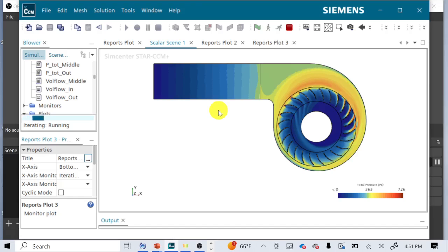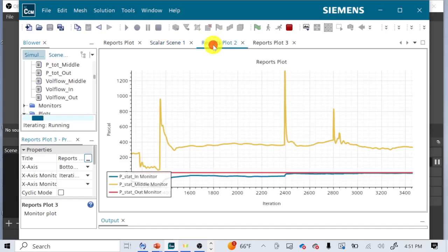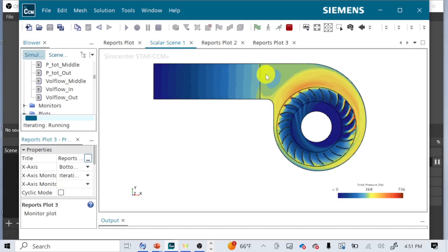Right there. So we're looking at the delta pressure across primarily this, but we should measure it at the inlet as well to make sure we know what's going on. So again, delta pressure across this outlet resistance section is what we're looking for primarily, but you should measure it at the inlet as well. That is an important part of this.